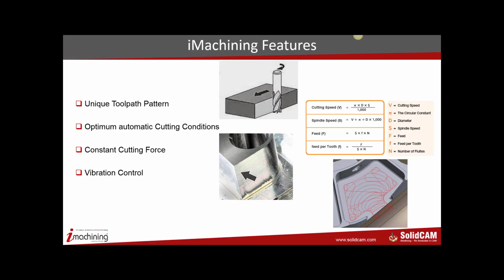Now, if you take iMachining and go to your cutting tool vendors, because they are the ones in the forefront of machining, the complaint that most probably you'll hear from them, unless they know iMachining in depth, is that you generate extremely high cutting speeds. Why do we generate these extremely high cutting speeds, which are 4, 5, or even 6 times more than conventional cutting speed?